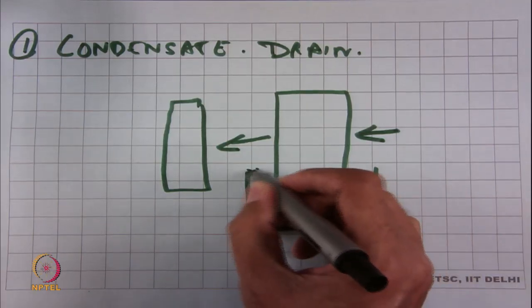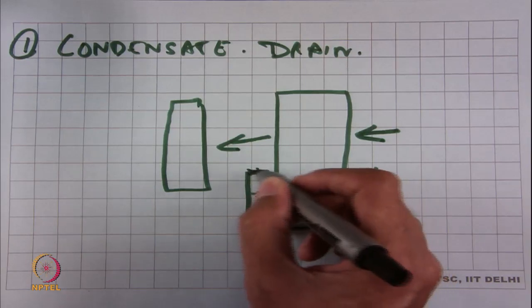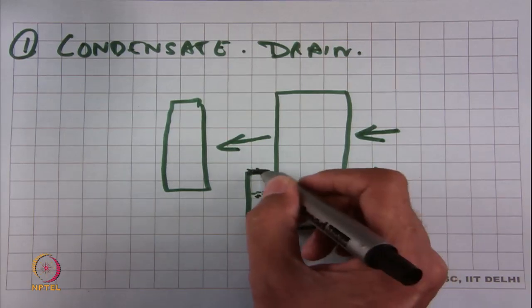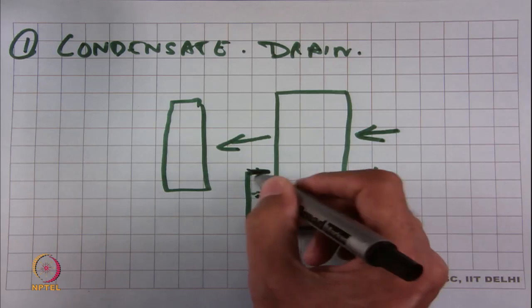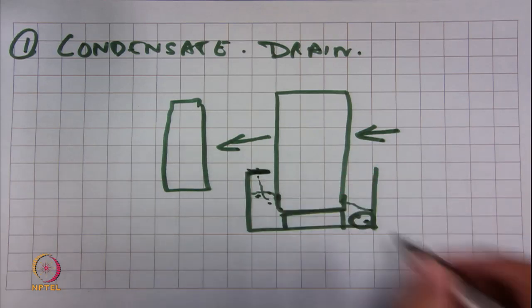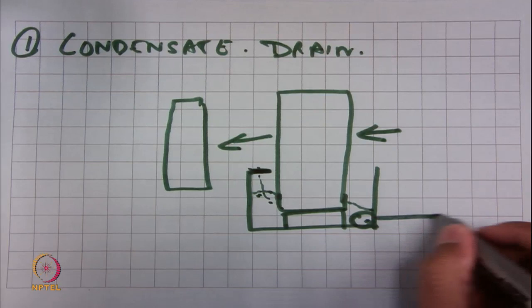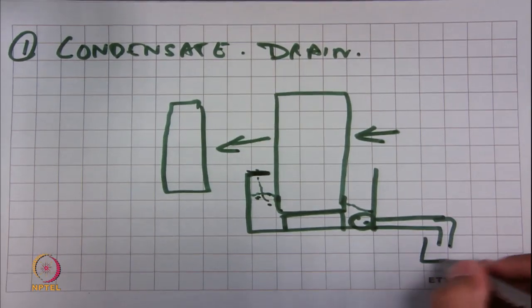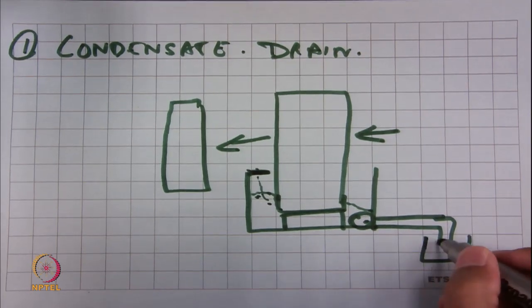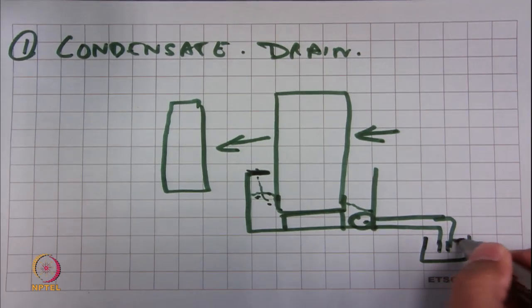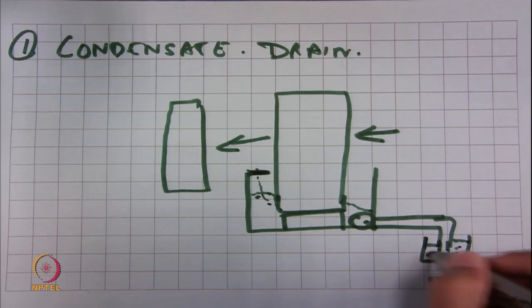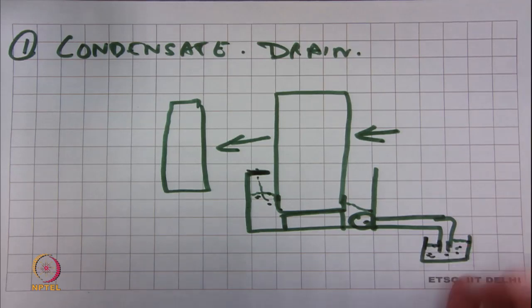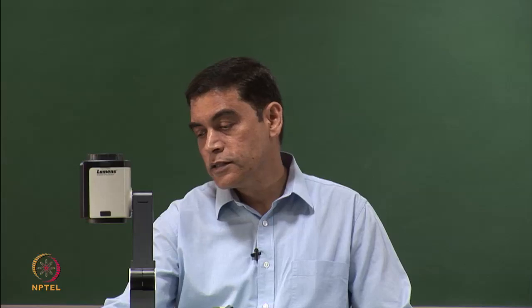So the design had to undergo some changes. The changes were to put in a redesigned drain pan, so that if there's any splashing, the water will not go out but will fall back in. And then the drain was to go out into a cup, a siphon kind of arrangement, so that the static was effectively addressed. Again, this is not something you would find in books. You need to find an innovative way to solve the problem when it occurs. It was totally unknown at the time we were making this design, and this effectively solved it.